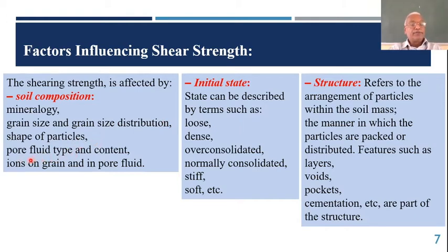Pore fluid means the water that will be there inside. Pore fluid type and content means whether it is viscous or non-viscous, having different unit weight, etc. And then ions on grain and in pore fluid. Ions on the grains, in the sense of clay minerals, you have seen that they are negatively charged or positively charged. Such properties which make up soil composition will affect the shear strength.